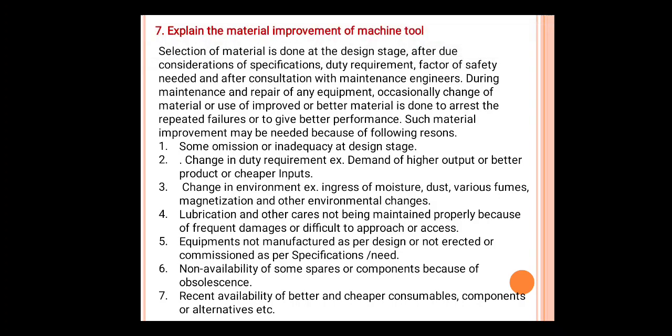Change in environment like ingress of moisture, dust, various fumes, magnetization and other environmental changes; lubrication and other care not being maintained properly because of frequent damages or difficult access; equipment not manufactured as per design or not erected or commissioned as per specifications; non availability of some spares or components because of obsolescence; recent availability of better and cheaper consumables, components and alternatives.